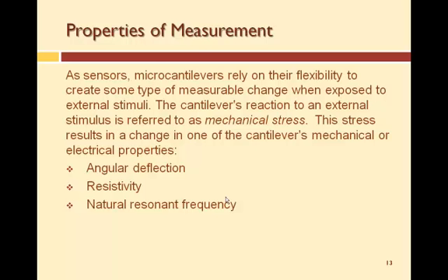There are materials where you take two different metals, right? Bimetallic structures. And when you heat them up, they bend. The old thermostats have a coil in it, right? Did you ever take one apart? If you heat it up, the coil either expands or contracts depending on how the metal is put together. So that's an example of that phenomena. In that case, heat is causing it to bend. But you can also create a coating that, if it absorbs something, it'll cause it to bend. So that's angular deflection.